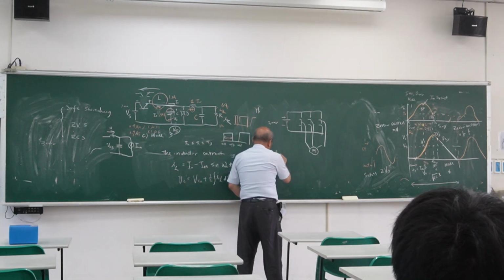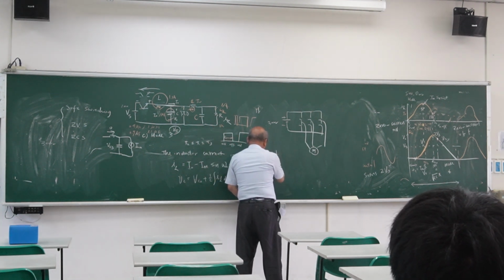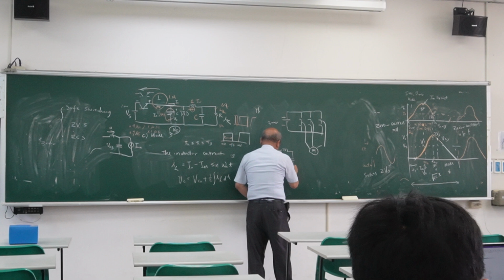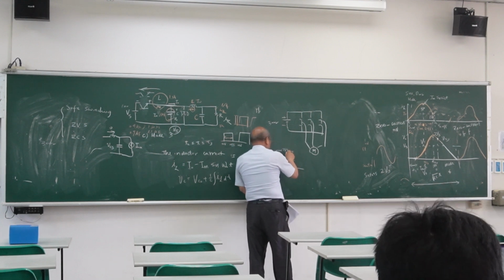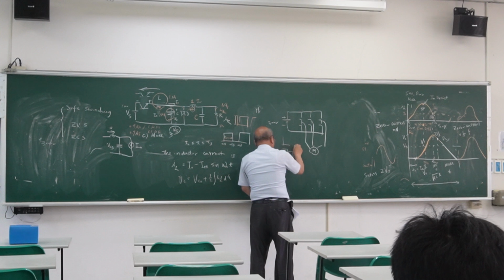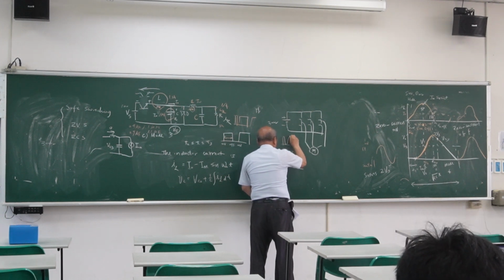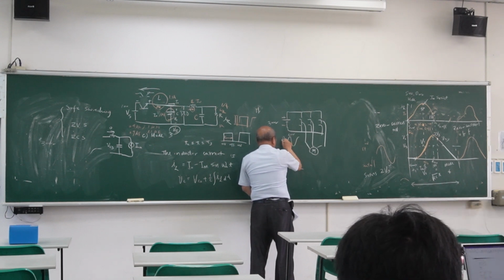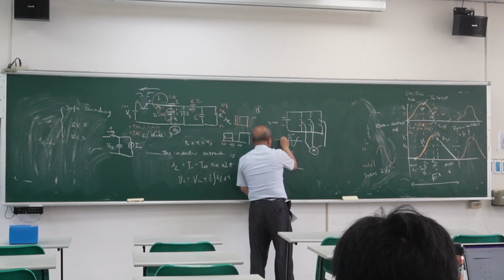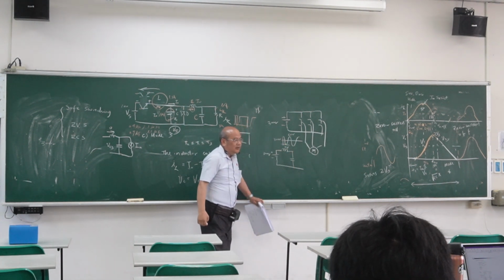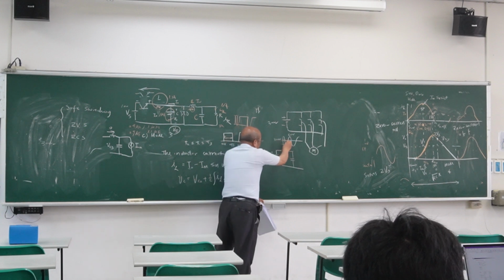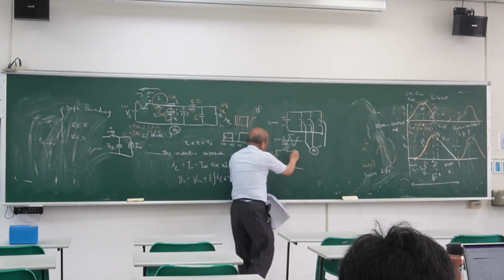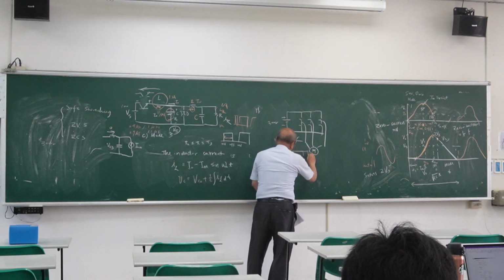You say it is easy. I can have 300 volt, but I can create L, I can create C, then I can get LC resonant, and at that point, I can get a voltage like this. So this is 0 volt, this is 600 volt, average is 300 volt. I get a resonant, right? Then I can get 0 voltage. Then I can turn on and turn off the switch during 0 voltage.